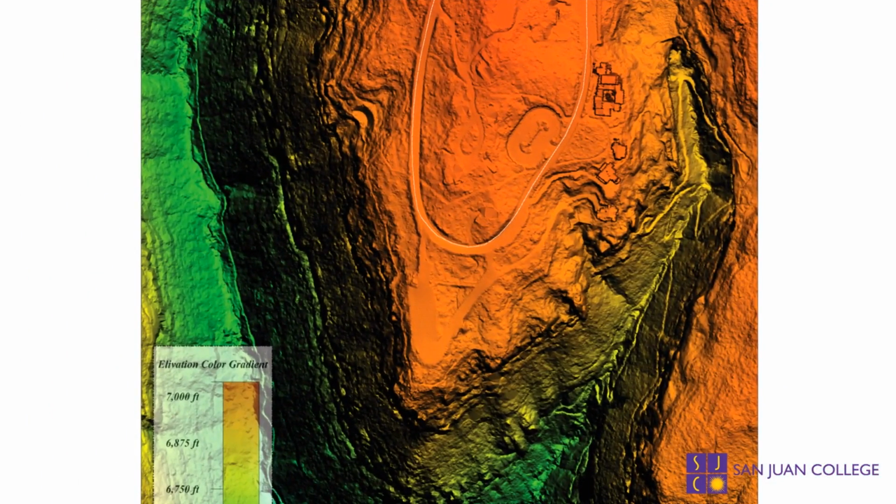The original data, since we've got cliffs here, automatic classifiers aren't real good at picking out the edges of cliffs. So the edges of the cliffs are missing. So we have them go in and do the edges of the cliffs, as well as the buildings are missing. So they're classified as non-ground points, but not as buildings. So we do have them go back in and classify the buildings. In this case, they're showing up.